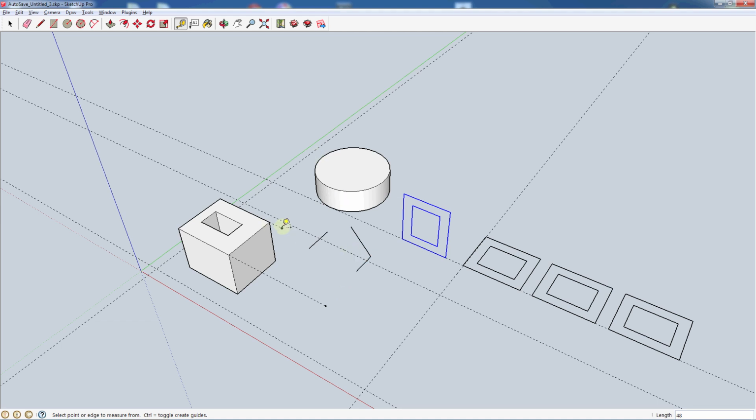You can create guide points, guidelines, and you can do basic measurements. This will take an area of an object and tell you what the surface area is. If you click on it, this one will tell you it's 104.72 inches square on this face surface. So we would be looking at that face surface right there. I don't use this a whole lot. You may find it useful in some things or not, but it is there.